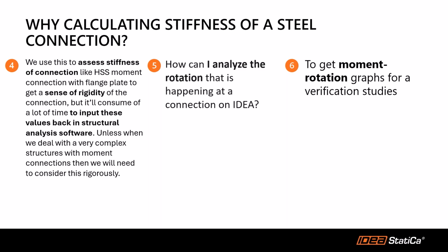So for instance, for the pre-qualified connections, they were comparing some experiments where they had the experimental moment rotation graphs, but then they wanted to test it in IDEA StatiCa. So this is also a good case because you get the moment rotation characteristics of the connections for whatever connection you are modeling there in IDEA StatiCa.